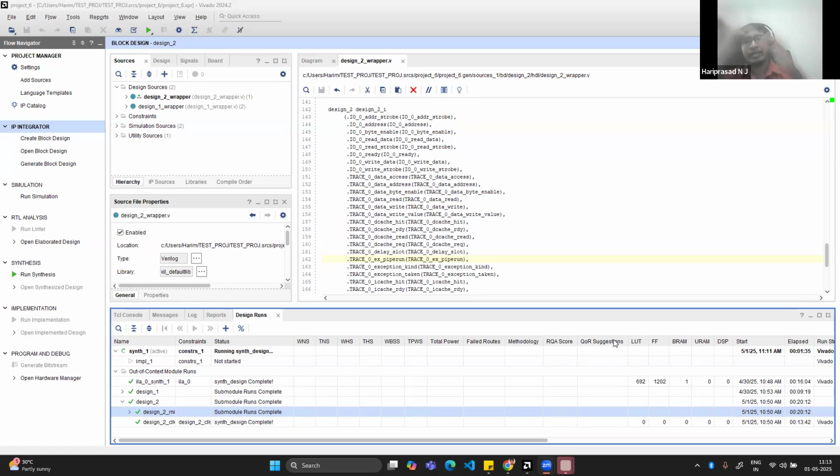When we say partial reconfiguration, one part of the FPGA is being configured. It is not that one LUT here and another LUT there. You mark the Pblock and reconfigure that Pblock. So block by block only is possible, because there will be some offset and from there it keeps being reprogrammed.